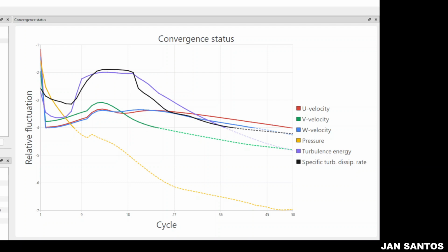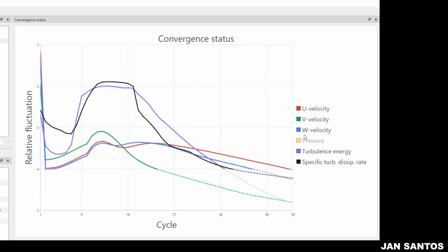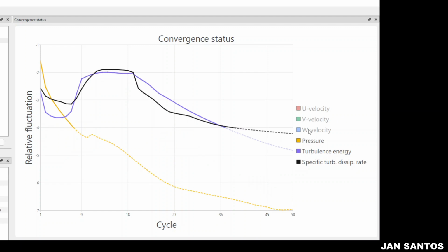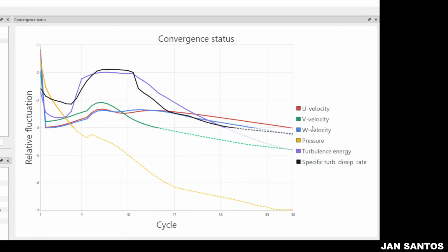Okay, so pressure and velocity values are particularly well behaved for the NACA 2412, and minor turbulence spikes early on are expected and do not indicate a problem as they settle later on. Okay, once again, they settle later on. So, apart from that, I believe that is going to be the end for this tutorial, since we now have a visualization of our results, that being the convergence status. Let me just go ahead and switch. There we go. I'm now back in the screen itself.